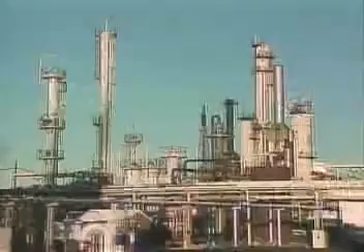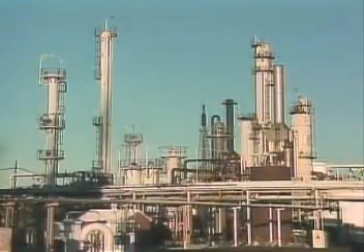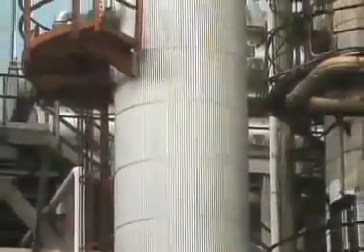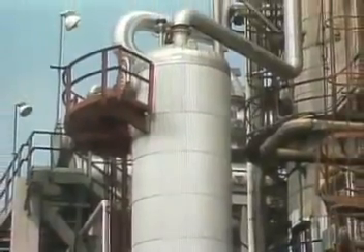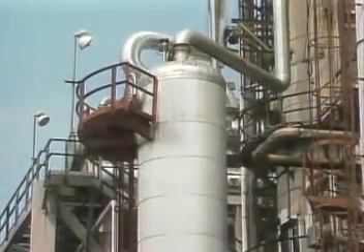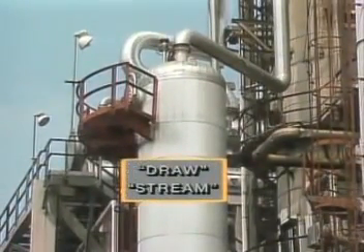For this reason, you may also hear a binary tower referred to as a two-product tower. Some binary towers separate one light component from a range of heavier components, but they are still considered to be binary towers because only two products leave the tower. Multi-draw towers separate a feed into more than two products. A product that leaves a multi-draw tower is referred to as a draw or a stream.